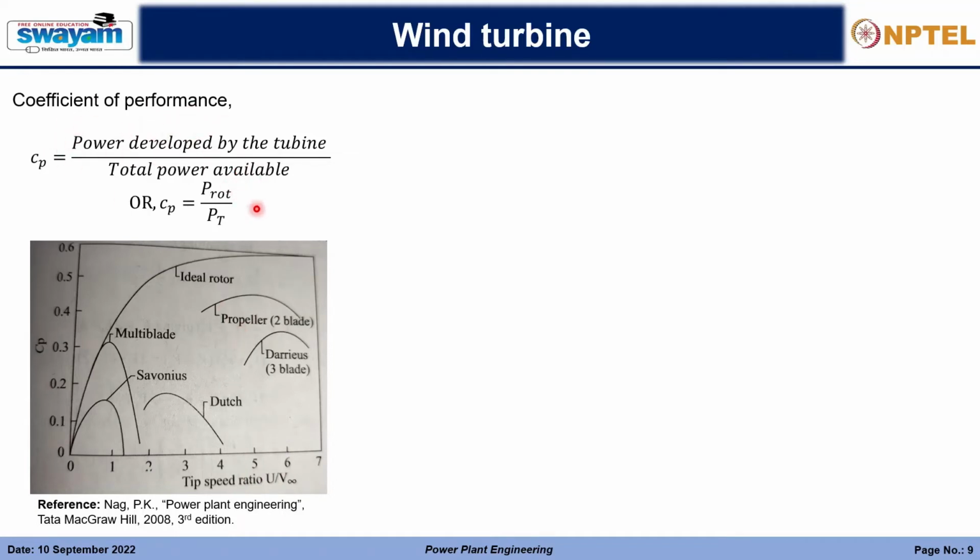performance, right? Again, as we have already learned, the speed at which the blades are rotating is dependent upon the angle of attack, or the angle at which the wind strikes the blades, right? So the angle at which it strikes the blade is now impacting the coefficient of performance. So it has a very great significance, and it is also impacting the load, that is the power generation, so how much power we need to generate.